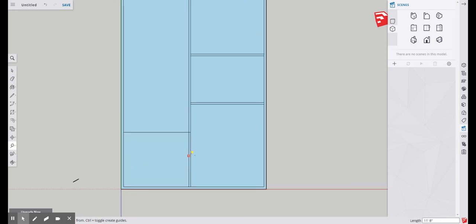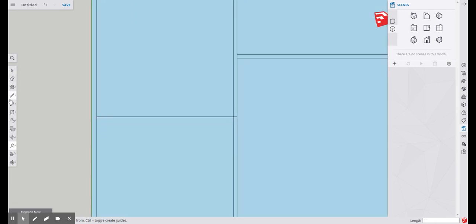Okay, next, just to get it out of the way, let's finish up this wall thickness. So 4.5. Okay, this is important. Notice how we already drew 2 walls. SketchUp starts to remember or pick up what you're actually drawing. So this little triangle, where is it? I don't know if it'll come up again. There we go. This little thing is telling me it's 4.5 inches, and all I did was hover. So it's starting to know that I just want 4.5 inches, so I'm just going to click it.